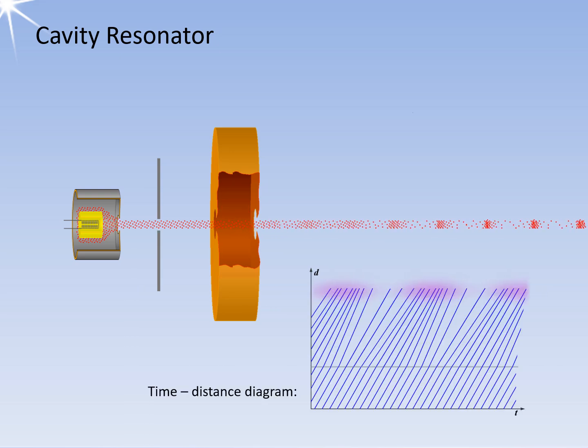An oscillation in the cavity resonator additionally influences the electron velocity. They are accelerated by the more negative potential and decelerated by the more positive potential. This results in a so-called velocity modulation of the electrons. Faster electrons catch up with slower electrons and form tightly confined electron bunches with them. Remember the name buncher cavity. There are only a few electrons in between. These are the electrons that passed through the resonator at exactly the point in time when the oscillation was at its 0 point.